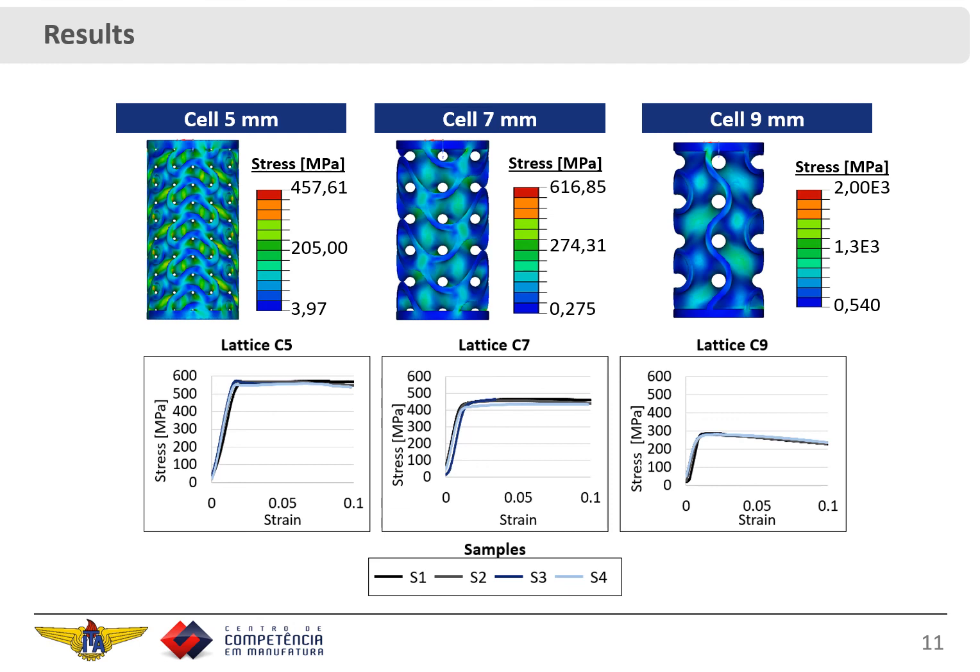The numerical experiment was used to bring more understanding to the compressive behavior, and we can see that while the compression is made, it builds up some shear stress at 45 degrees, and this will be responsible for the failure of the cell. But as I said, we don't have a perfect match between the stresses measured experimentally and numerically.